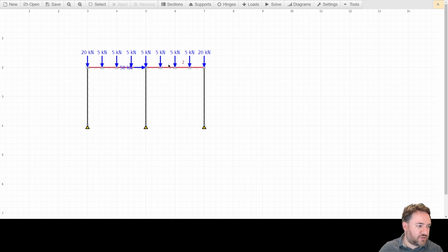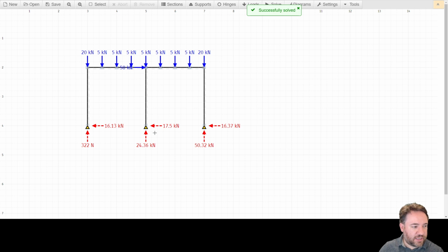for my structure, the vertical loads from my joists, the vertical loads from the trusses that are on either end, and I have the horizontal load from the earthquake. I have defined all my sections, and I have defined my boundary conditions. So now I can actually run. How do I run the analysis? I just hit this button here that says solve. And you see right away, it gives me what are my reaction loads. So those are the reaction loads at the pin, at all the pins.